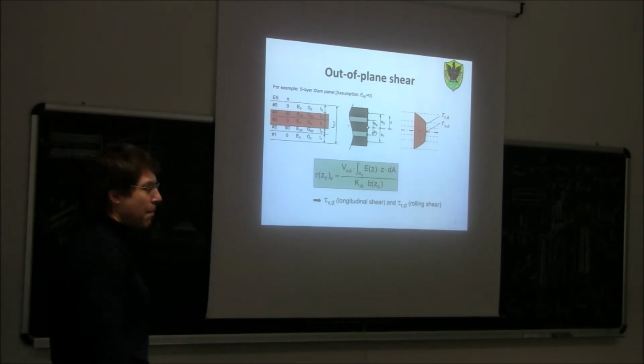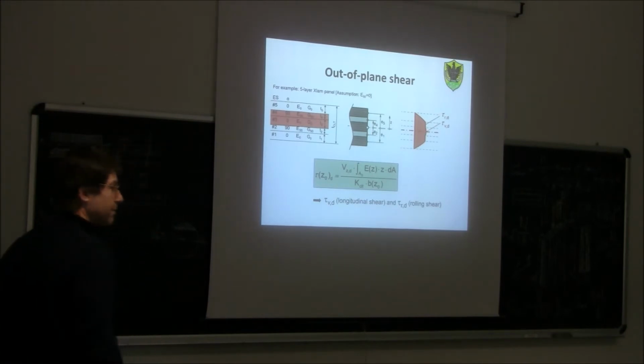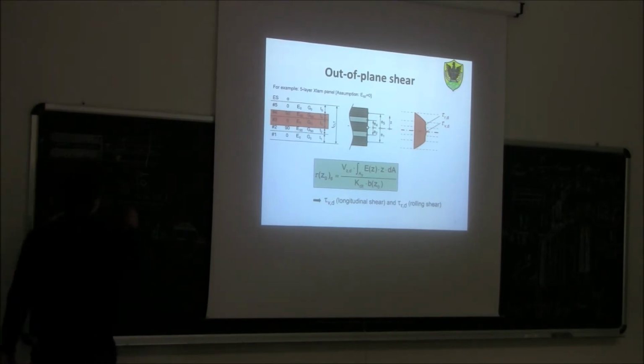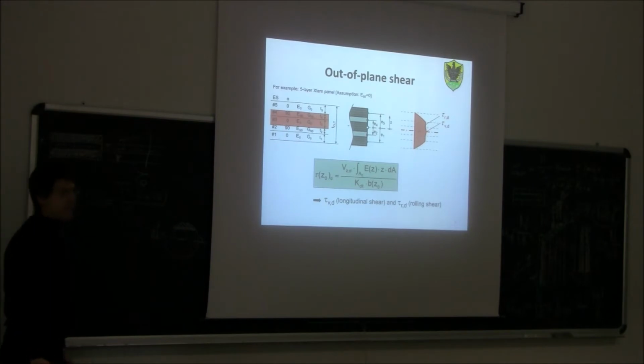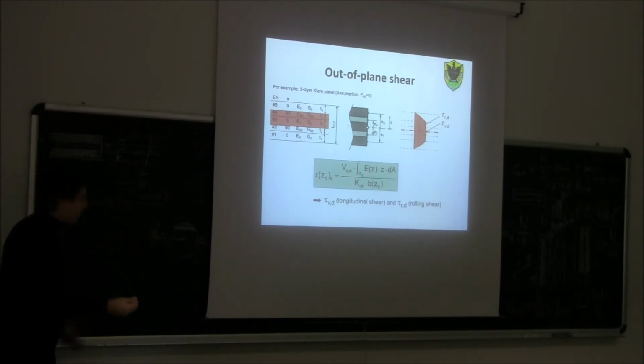what? The second moment of area of what? Of the resisting, or we call it the effective, cross-section, with respect to the neutral axis. In this case, the neutral axis is the centroid of the resisting cross-section, which is also the centroid of the whole area anyway.